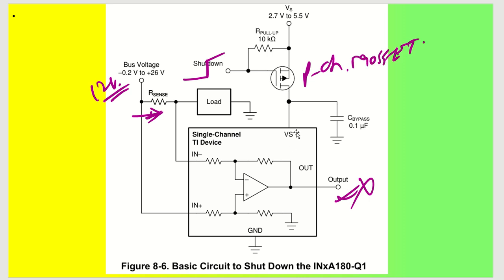So what is happening is, this particular supply voltage, let us say 5 volt, we are giving here. So 5 volt has been biased at this gate also. So this is my gate. The gate is also biased with this 5 volt, so this is my source and this is my drain, right? Since it is P channel, this is not on.